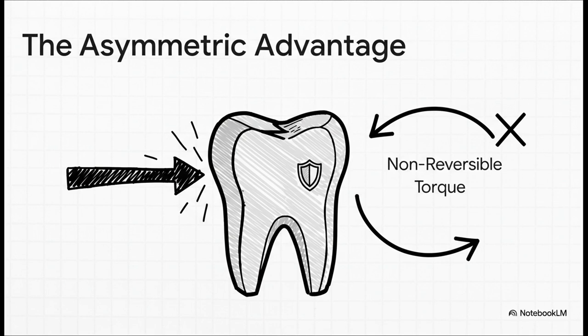In things like power generators or heavy-duty winches, the torque is pretty much always going in the same direction. So engineers brilliantly redesign the tooth so that its flanks, its sides, are optimized for that one direction of force. And according to the work of Allman, DeSalvis, and Gonsalves from 2021, this clever trick can massively boost a gear's load-bearing capacity and its resistance to wear and tear.